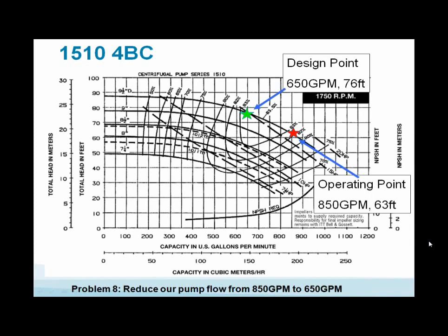System will work, but it's going to use a lot of extra brake horsepower. You may have some zones that are noisy, where the velocity is so high it may be a problem. So how do we balance this? How could a system sizer help us? What can we do? Well, remember that scale 5 on the B&G System Syzer, the manual one, or the CV charts in the Windows-based version where you put in the known and unknown flows and heads. That's where these square charts come in handy.